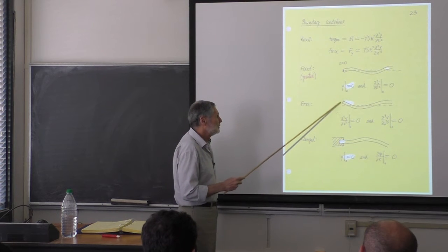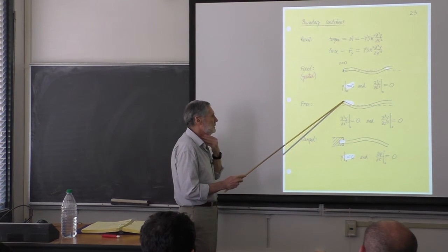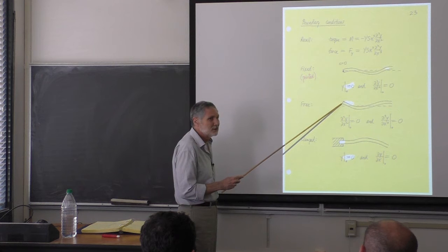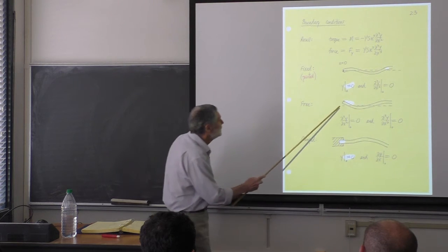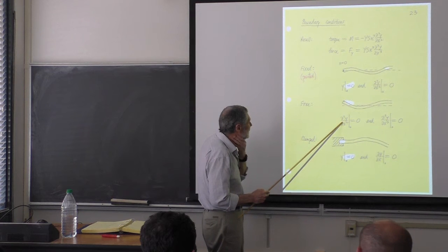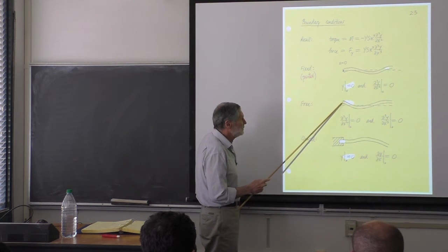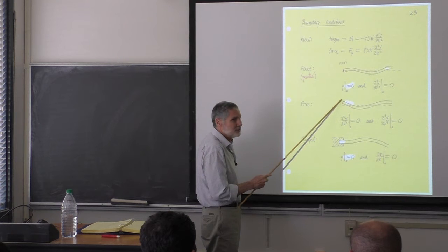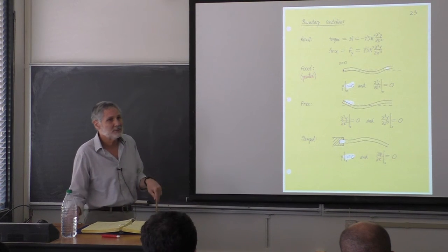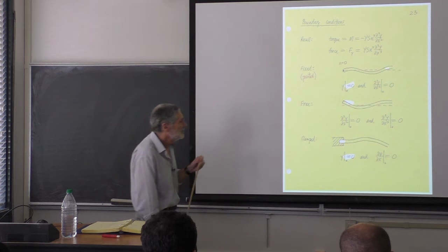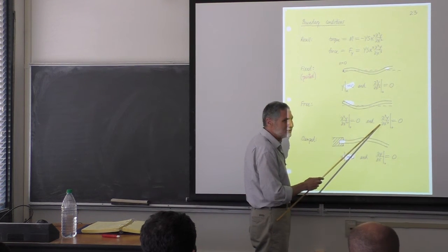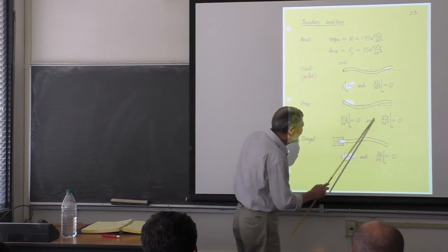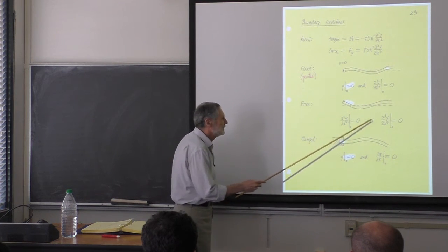Okay, here's a common one, free boundary. So here y does not equal 0, but first of all, what's the torque? Can this bar be exerting any torque on this end face? No, nothing there to balance out the torque, so it's got to be 0. So we've got to have 0 second derivative. Similarly, there can be no force because there's nothing there to balance out the force. It would have infinite acceleration in the end. So we look up here and we see, okay, that's 0 third derivative. So the conditions for the free end are this.